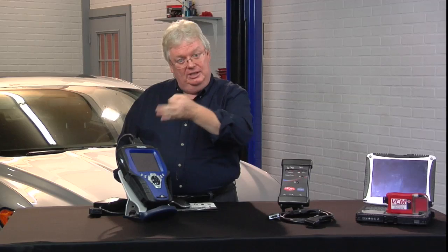That I know about. As far as 5 different CAN buses, I'm not sure we got the question correct, at least in my head, but I'm aware that they may have expansion buses, and that's in that training program, Fred Kicks the Can. Expansion buses for chassis, because there are too many riders on the bus, even with CAN, and also expansion buses now for powertrain. We're seeing that. So it's not just pins 6 and 14. It could be 2 or 3 or 4 other pins.